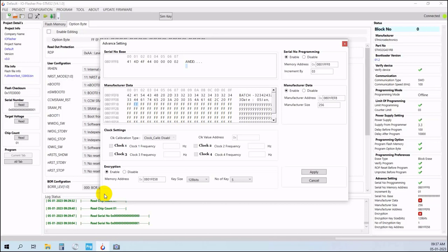the device. Now once you interact with your server in a controlled environment, it will exchange these new keys, right? These new keys which you have generated, it will exchange those keys with the server, and the further communication will be switched to those keys. Then your first key, which is being used by the device, will not be used again. This is only one-time use for the production. And now in this way, each device will have a separate key, which is only known to the